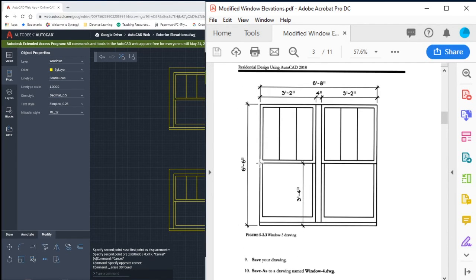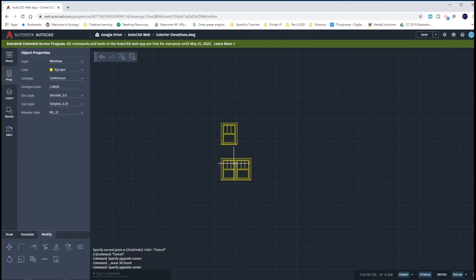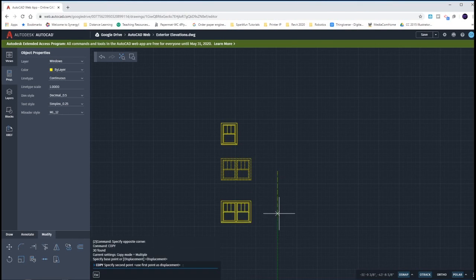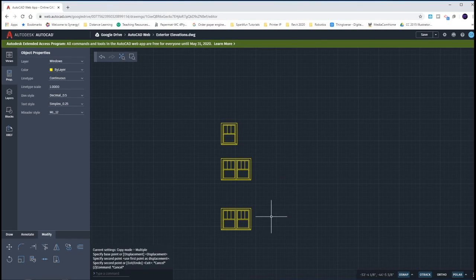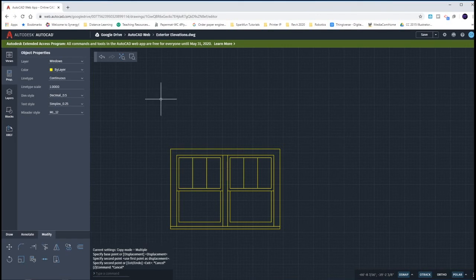I also want to stretch out this secondary part here down on the bottom. They're currently 30 inches from this line to our base. And so if I want to get up to 3'4", which is 40 inches, it means I want to stretch that bottom part by an additional 10 inches. So if I stretch the bottom by 10, and then I want to get a total of 20 inches high, that means I'm going to stretch the top by 10.